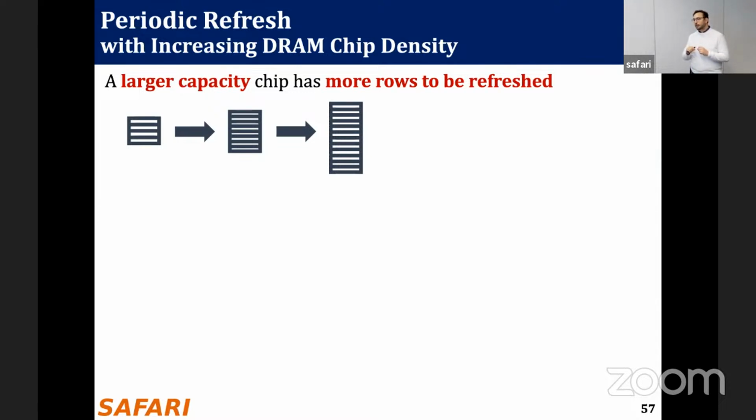Okay. But of course, when you send a refresh command from the memory controller, it's a black box inside the DRAM chip, right? So you do not exactly know what row is being refreshed, and if there is any parallelism there. So we do not know all those. Okay, I see. But in this work, actually, we do not rely on that refresh command as well. How we refresh is we send activations. Okay. Yes. Thanks. Sure.